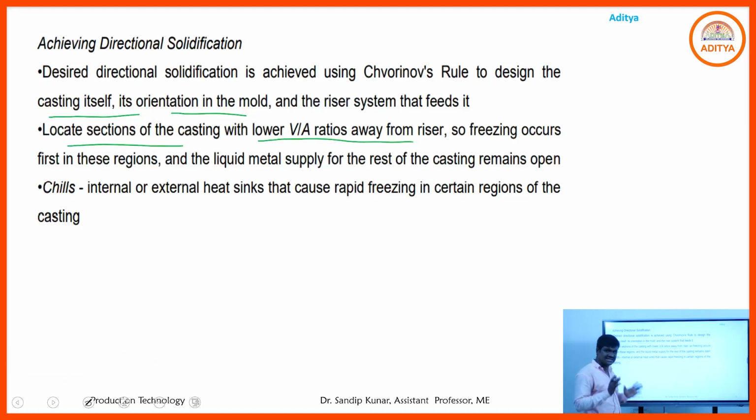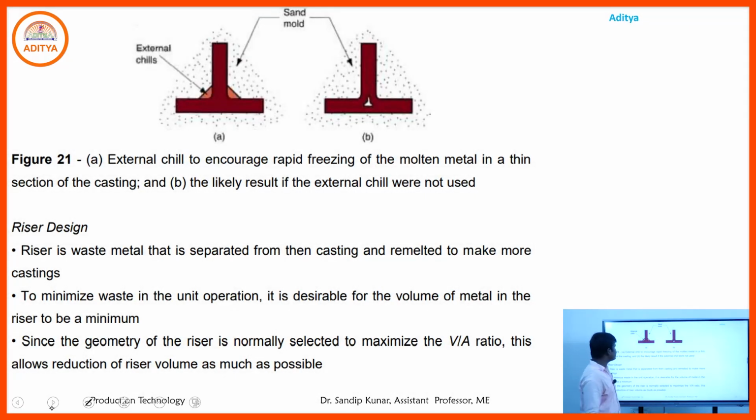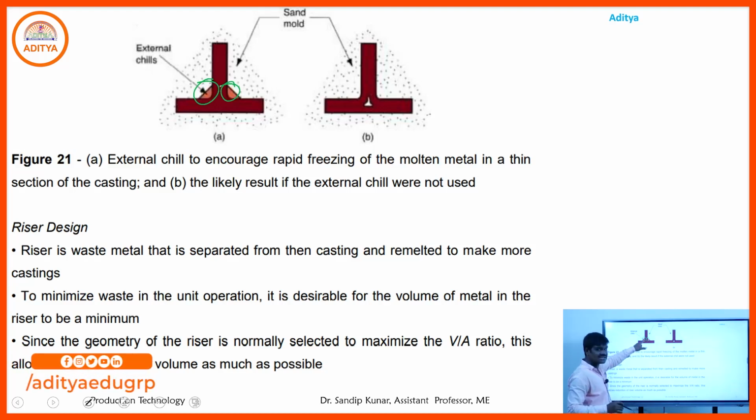Sometimes we use chills for easy or quick heat removal. When we apply chills to a particular region, more heat will be removed from that region, and solidification will start at that surface also. Here we have seen the external chills, and sometimes we also use internal chills. With external chills, more heat is extracted in that particular region, and solidification starts at that surface.